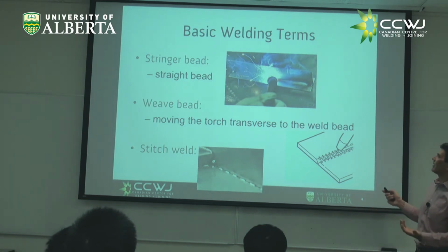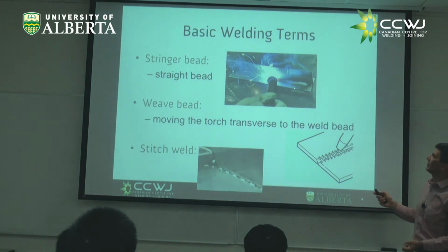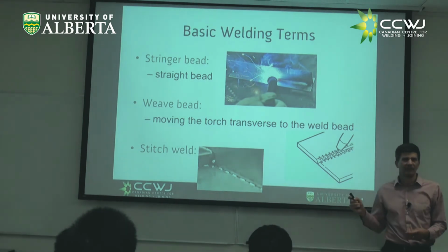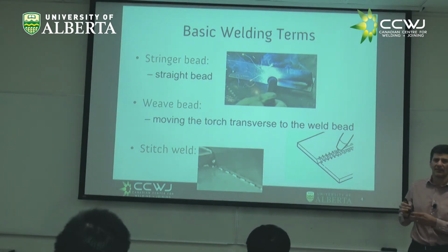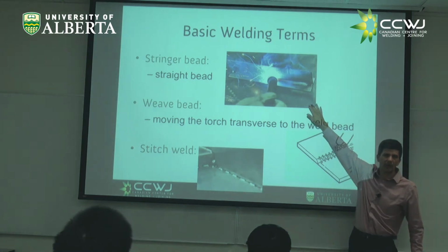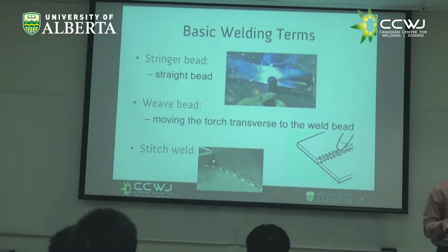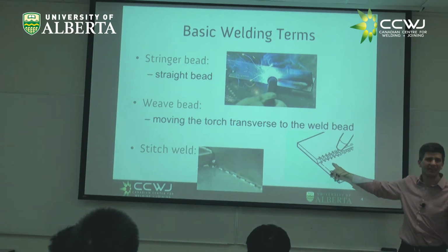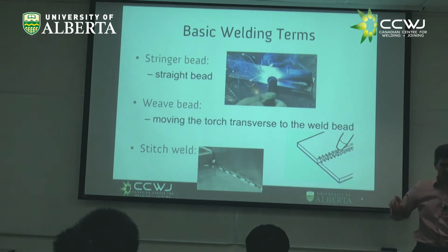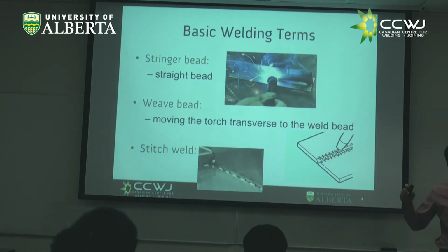Which weld is likely to end up harder, this weld or this weld? This is likely to be harder because it has less heat, it's going to cool down faster, right? Which one is more likely to be sensitized? This one, if you have stainless steels, right? Super interesting. In welding, you're going to see how many concepts you either learn about or heard about. They come together and have a direct implication.